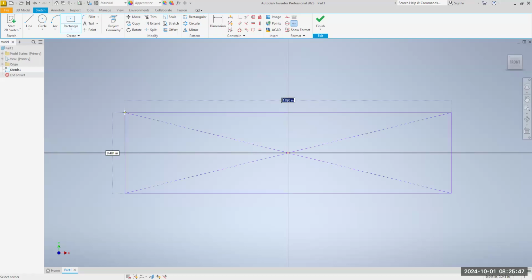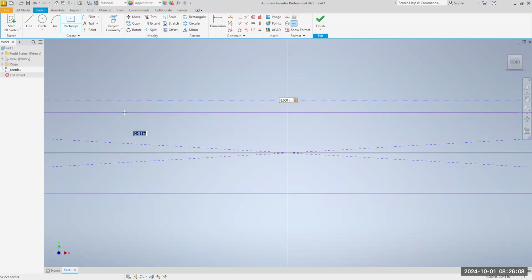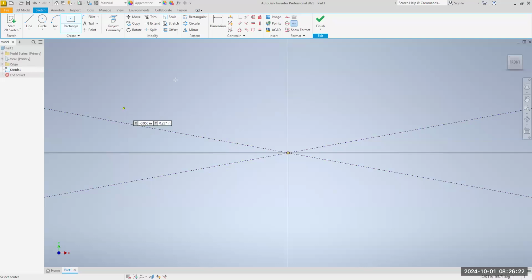All right. Now it's asking for dimensions. So the overall length of this part, which is shown in blue, we're going to type in 8. Do not enter. Hit the tab key. And even though your geometry has gone off the screen, the vertical dimension is still there in blue. And we want the vertical dimension here to be 1.5. Enter. Now do a right click, select OK.